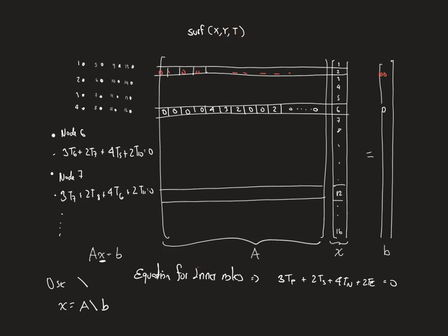So in this example, the 4 times 4 matrix is going to be like the coordinates of the mesh. Okay, these coordinates we can simply create with meshgrid. So when you have this, you just take these x and y matrices to plot the whole temperature field.